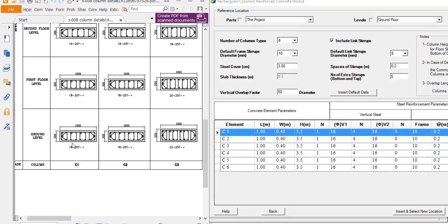The main vertical steel is 18 numbers, 20 dia. So we keep it as 1, for the width we put 0.3, and then we just keep the height the same. And it depends on how many numbers of column types 1 in a ground floor. In case you have more than one, again, you can type it simply. I'll just keep it for now for our example.